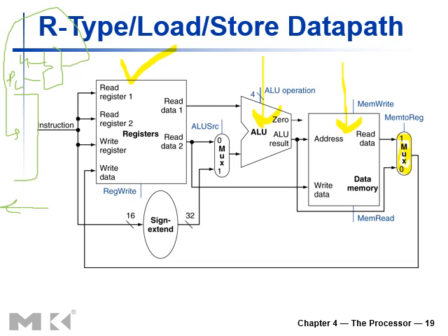We've got two separate paths, and this MemToReg signal is responsible for selecting the data. If we route the data from the ALU to the register file, we set the signal to 0. In that case, the data is just routed back to the register file.